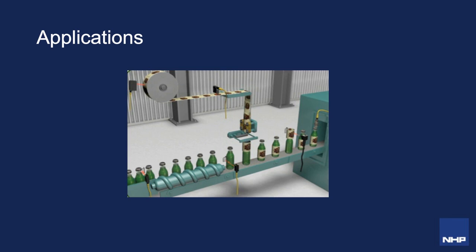You have access to both sides. Light's completely blocked by the liquid, so if it's too high, it will still be blocked. And this would allow for some level of environmental contaminant withstand as well, more than what a retroreflective would handle. But you don't necessarily require this, as it looks like it's a clean environment and there's not a great sensing distance required. Technically, you could use a capacitive sensor as well, so provided the liquid is present at the level and it significantly changes the capacitance, you would detect this through the glass. However, that would also ignore contaminants in the environment, but you would need to install it closer because of the sensing range. And if the bottle isn't perfectly in place, it might actually knock the sensor out of place.